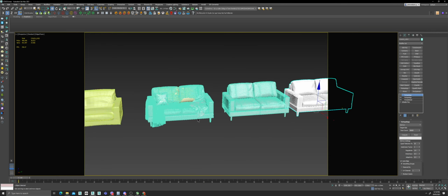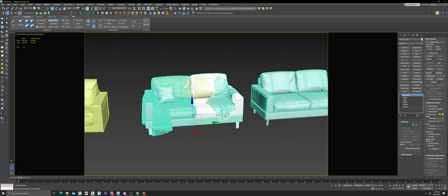Okay? Because as you can see here, the original model has 3 or 4 texture maps. So what we're going to do here is that we're going to combine all those textures into one material na lang. In one diffuse map. Kasi kung 4 materials ka, you have 4 diffuse maps, right? 4 reflection maps, 4 normal maps, for everything else.